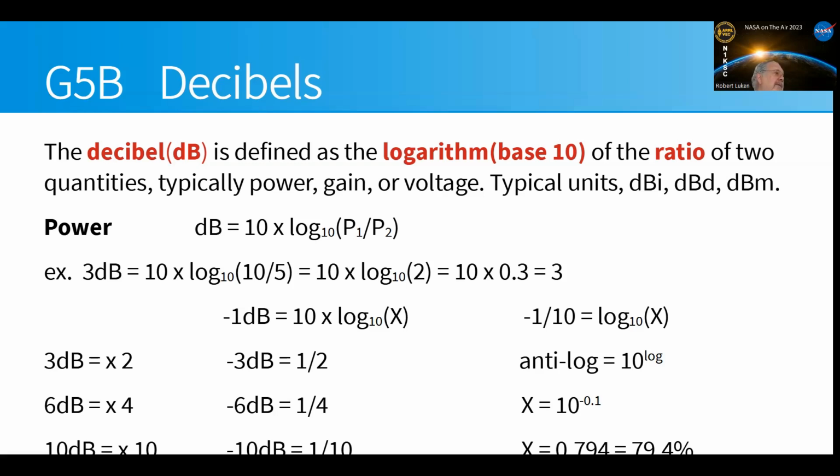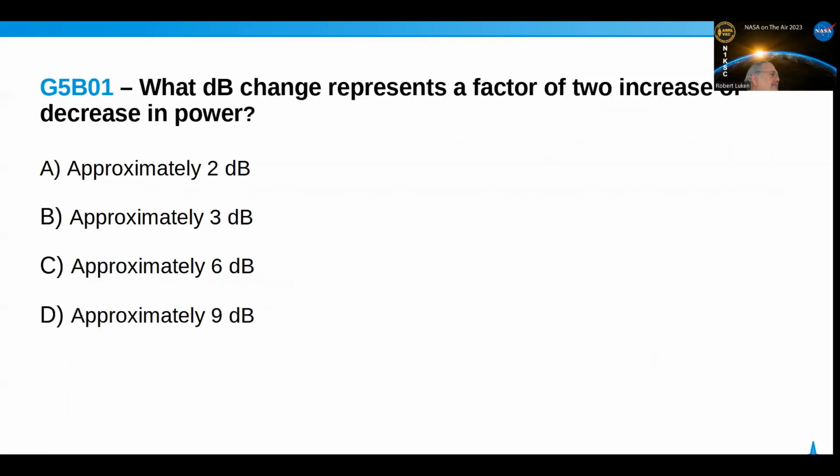Because we tend to say a 1 dB loss is negligible. It's not really that negligible. And if you're talking about doing really weak signal stuff, like moon bounce, it's really significant. So hopefully you don't get that question, but just remember that it's 20%. You don't have to work it out.